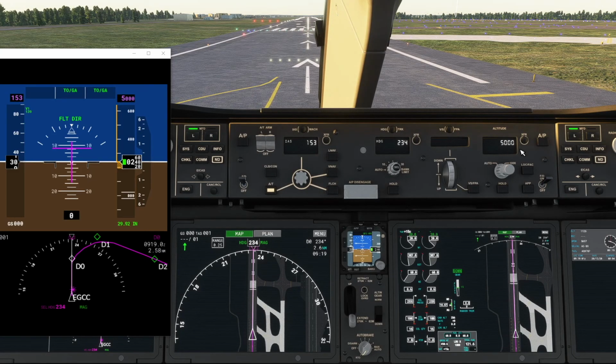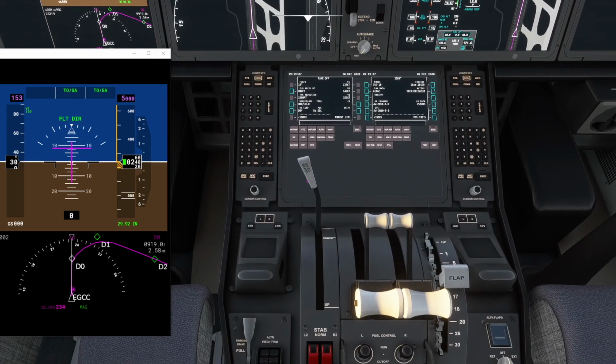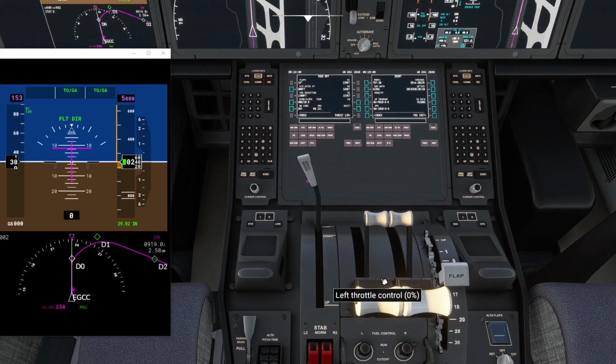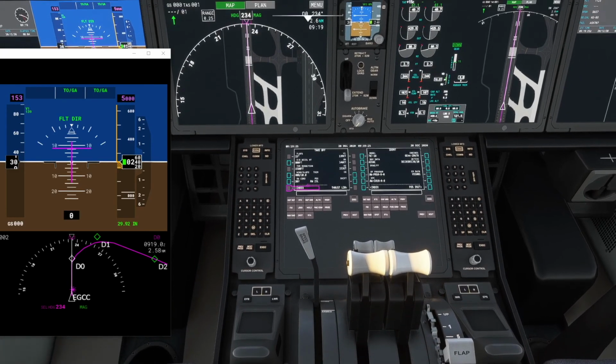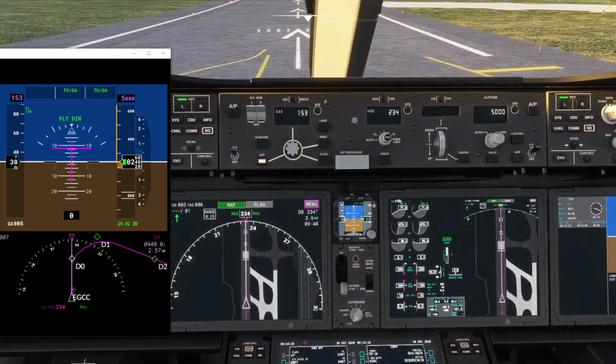We'll release the brakes and I'm just going to peek down and find the TOGA button, which is just here on top of each thrust lever where it says activate TOGA. There's one button on each thrust lever, and you only need to press one of them once for the aircraft to go. So we're fully ready now, and go ahead and click that. Thrust levers come up, and we begin our takeoff roll.